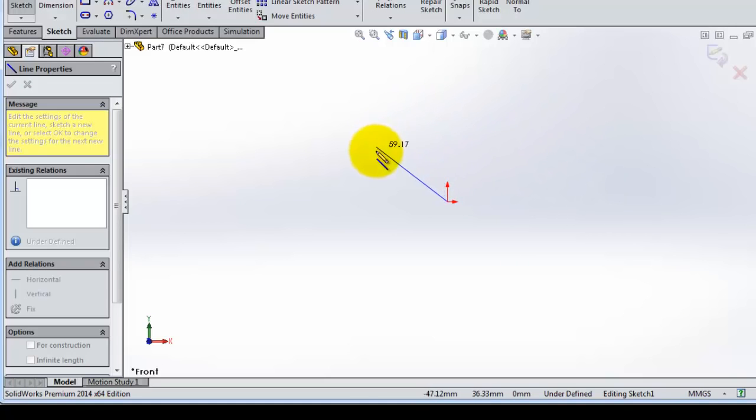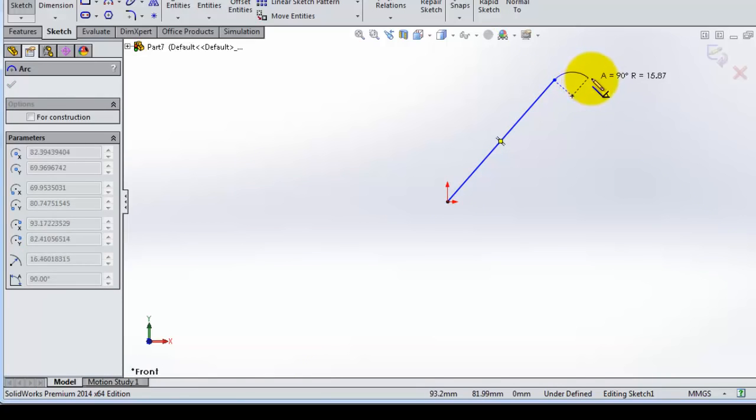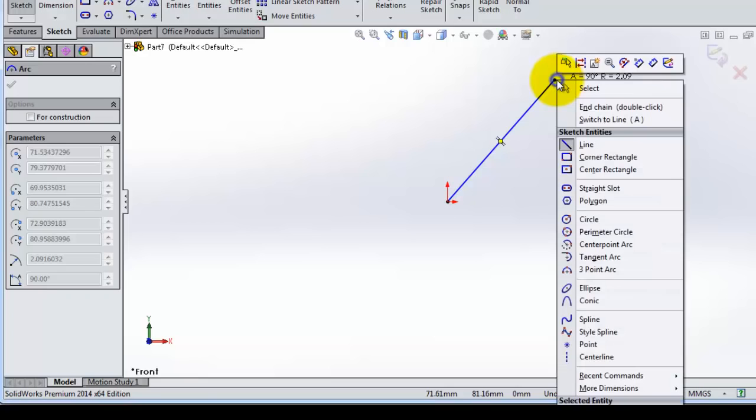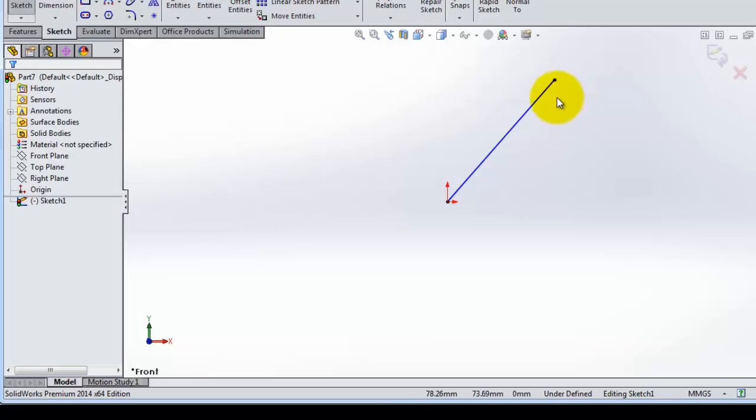That is a helpful tool, so you know the approximate length instead of making small lines or bigger lines and then redimensioning them, which might mess up your sketch. You can pick it to be, for example, 100 millimeters, and when you click, you're selecting your point, and you are still able to use the line tool. When you are done, you can press escape or right click and select end to finish your line tool.